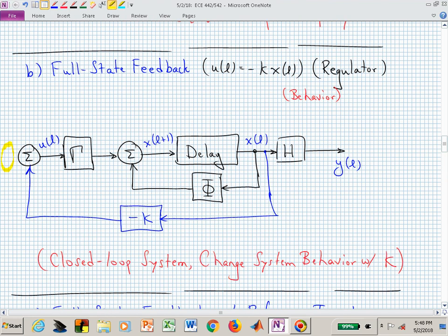And again, that's the closed loop system, because I've now tried to indicate that with the blue. I'm physically going in and saying I have the ability to go in and access the full state vector. If that's 10 different elements, I can measure each of those, scale those through the gain matrix K, and use that to change the dynamic behavior of my system.